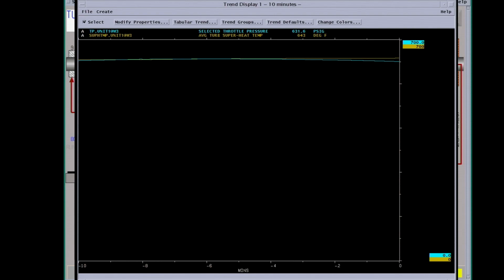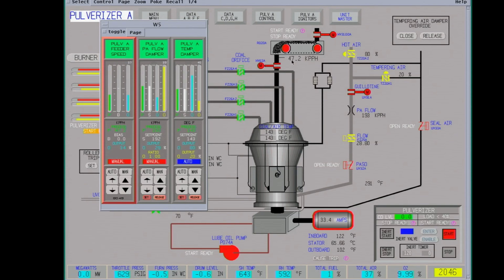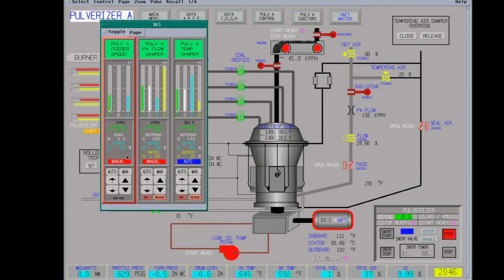You can see our pressure's diving off a little bit. Throw a little more fuel on it. The key is to hold the pressure even. Otherwise, your heat soak for valve transfer will take a lot longer. That's quite a little too much. Probably want this closer to 42 to 44, something around there.